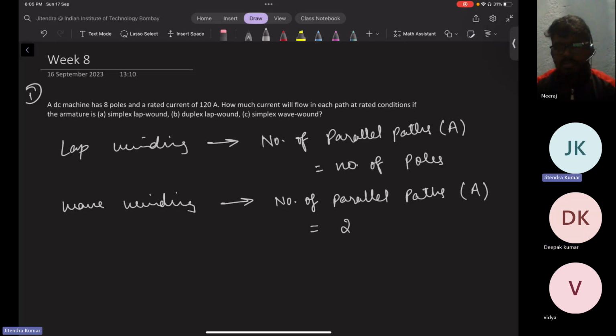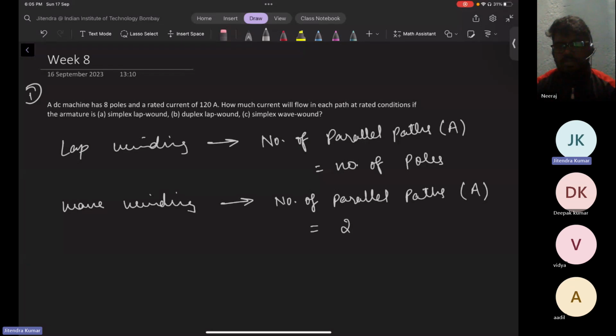But you are reducing the current in each winding, so you are reducing the I squared R loss in that particular path or each coil. In that sense, heating is reduced, but the insulation level will be the same. It will not depend on the current level, it will depend on the voltage. That is correct, Deepak. Any other thing?